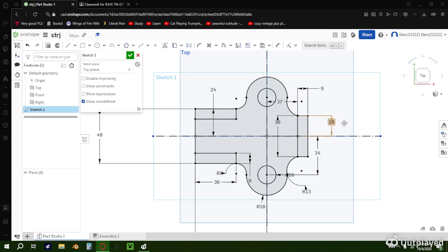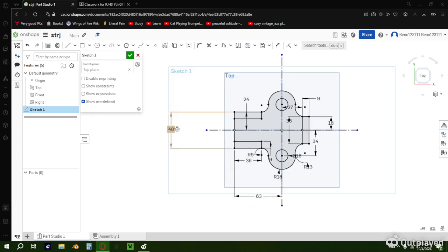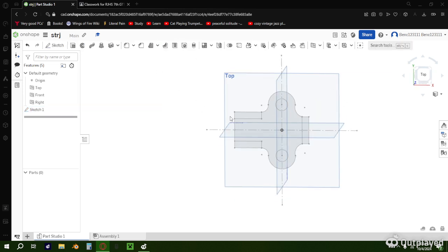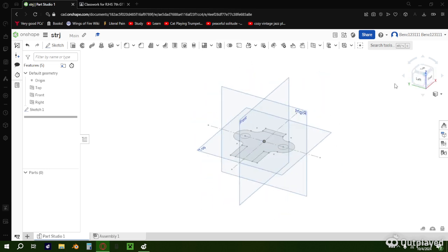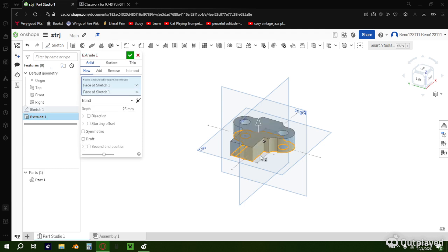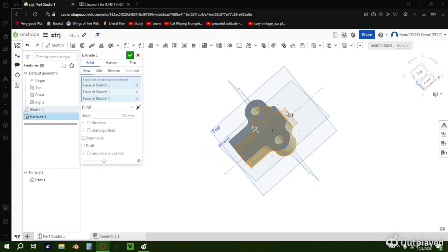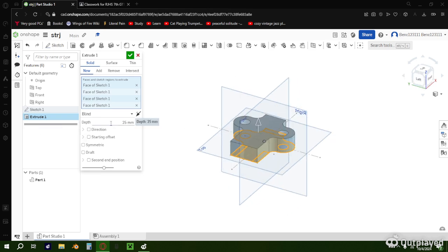And once you're done with all this, it's finally time for an extrude. Now when we're extruding this, I know this is a bit messy. You might want to move your things around to clear it up again. But now that we're going to extrude this, we're going to go to the side of it, or rather go back to the top. I recommend using this angle because it's easier for me to see when I'm extruding. But from here we want to extrude everything in here. All the sides and all the disconnected pieces. And then we want to offset that a total depth of 9.